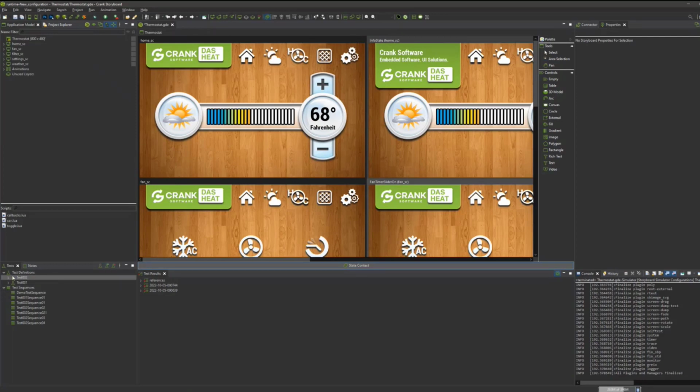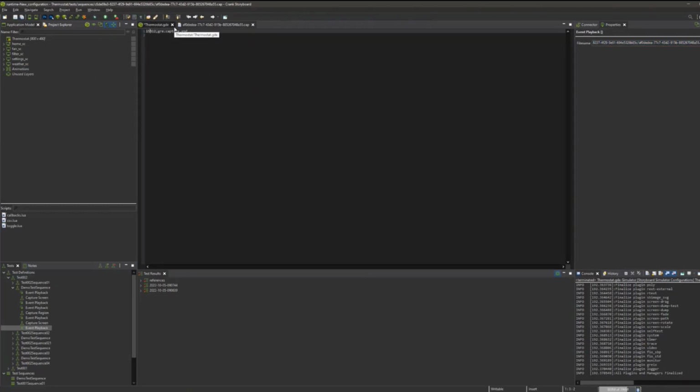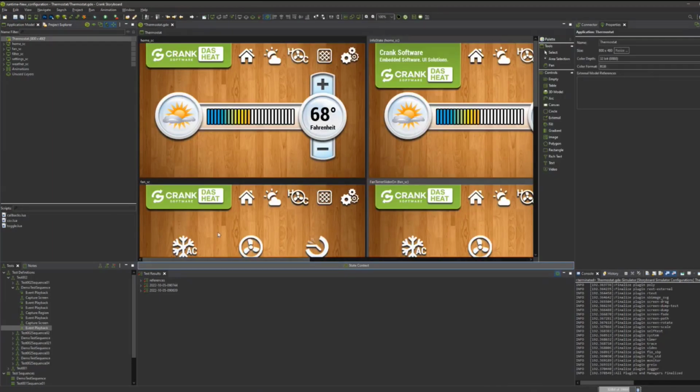It'll of course be a little bit long, but I can do one thing to shorten that quickly here. If I modify this from 15 seconds, which is that long delay at the end, I can bring that down to say 400 milliseconds. It doesn't need to be a long delay at the end. That small change will allow us to have a faster playback than we did the first time.